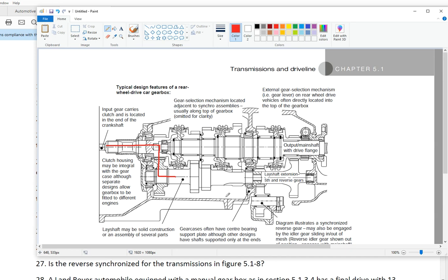In high reduction, you get it in the first gear, and this is the power flow path. And of course via the synchronizer if you want. So synchronizer and to the output shaft. Okay, so to engage the first gear, the synchronizer sleeve is to